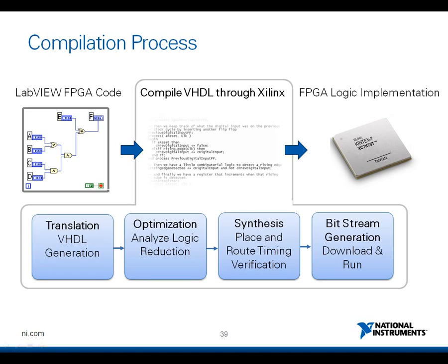Most of the time will be spent within the Xilinx tool chain in the translation, optimization, synthesis and bitstream generation phase. Whether you are programming your device in LabVIEW FPGA or VHDL, you will need to go through this process, which takes anywhere from 10 minutes to several hours. The overhead in converting the LabVIEW FPGA code into VHDL is actually very small.